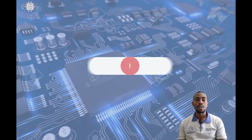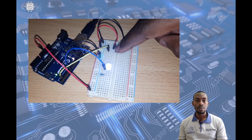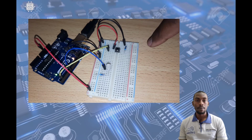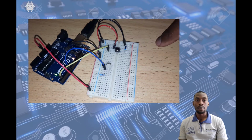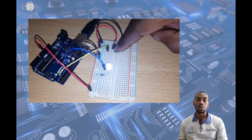In this class, we talk about digital inputs to the Arduino. And as our demonstration for this class, we shall develop a program using an LED and a push button. The implementation will be such that when you press a button, the LED turns on, and when you release the button, the LED goes off.